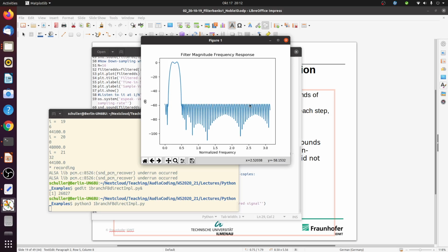So the factor here is 0.001, right? 1/1000. So it's actually quite a small value here in the stop band. So that's good. And actually, by experience, -60 dB is enough to make signals in the stop band range inaudible. And this is what we want.